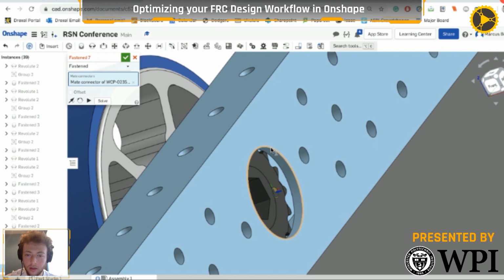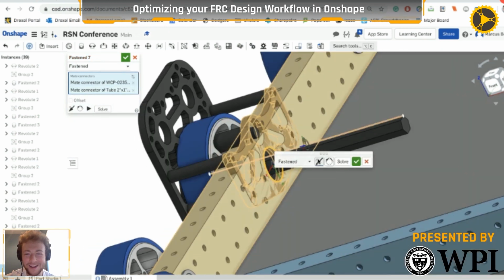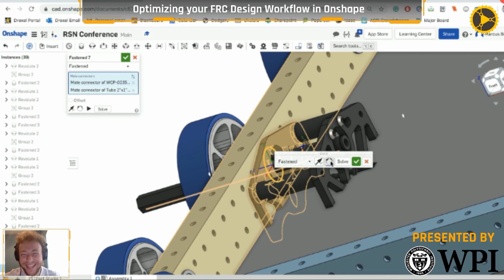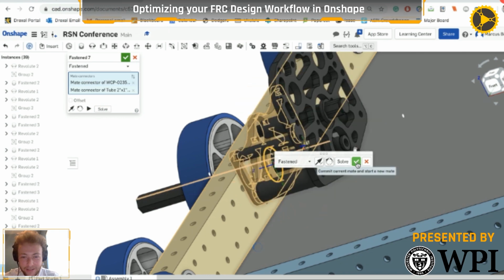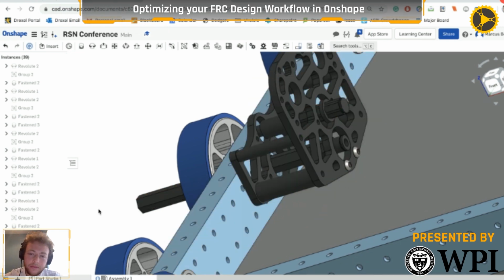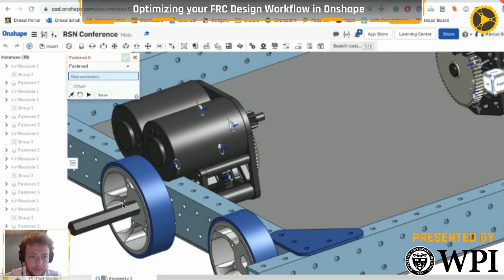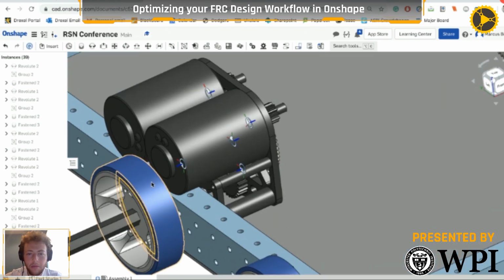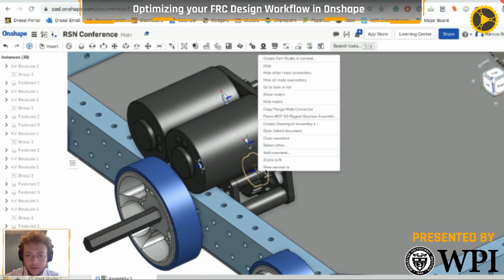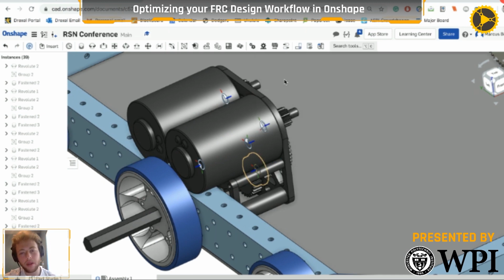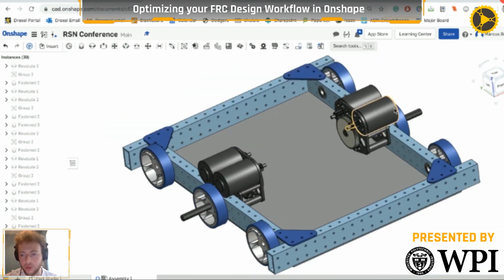Our CISC 101, the first question we asked today is, Hey, Rick. He said Onshape gets really slow when there are lots of parts in an assembly and you're trying to do the mates. Any tips to help with that? I would say the big one is be smart about what you have open and simplify your geometry.